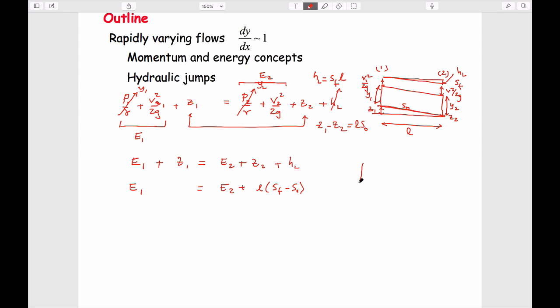What we chose to do was take our channel side on, that we can look at here, and define it in terms of a flow, not the total flow that we have in the channel, which we've always called Q. In terms of this geometry, we take the amount flowing per unit width, which we called lowercase q, and if we have a channel width of b, lowercase q is equal to the total volumetric flow rate, meters cubed per second, divided by the width of flow.